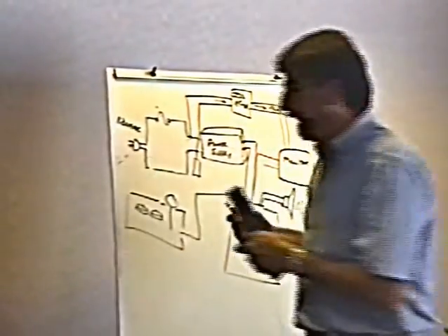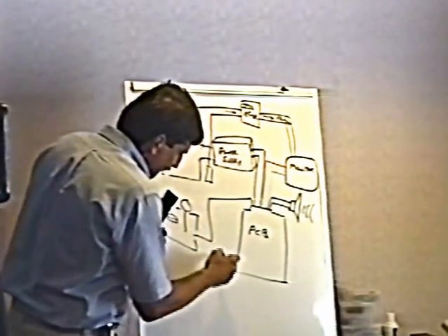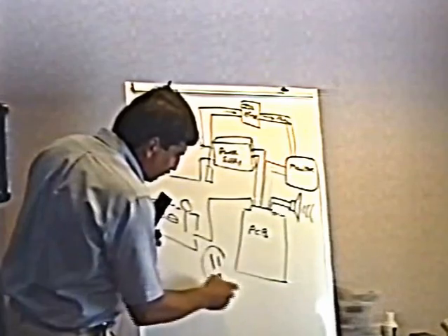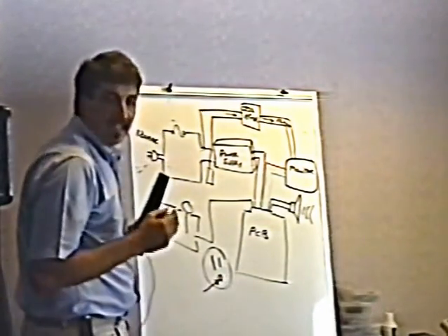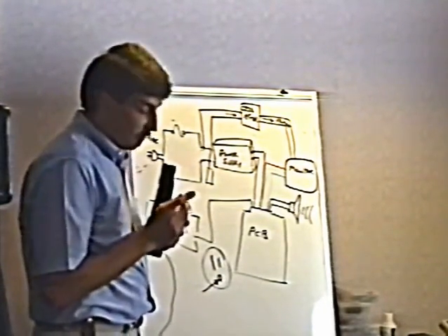The next pin up is called frame ground. It says FG, frame ground is what that really means. This is AC power, frame ground. Not field ground, although some people call it that. It's actually frame ground. This is where the third wire connects. This is where the third pin on your AC power, I discussed this with you before, the ground pin, the green wire, that's where that's supposed to go, on frame ground.